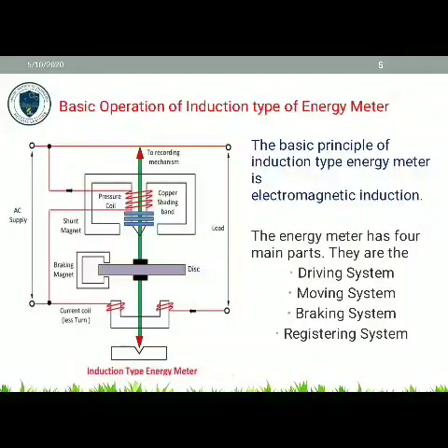Basic operation of induction type energy meter. The basic principle of induction type energy meter is electromagnetic induction. Construction wise, the energy meter has four main parts. They are the driving system, moving system, braking system, and registering system.